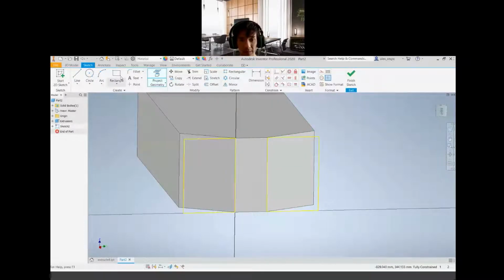Okay, what I want you to do next will be to create rectangles. The important thing for your rectangle will be to ensure the first point snaps towards this endpoint here. You have to ensure your rectangle's first corner snaps towards the endpoint here. Then please drag until here. You see a collinear constraint here. You want from this corner to touch till here. Okay, that's the first one.